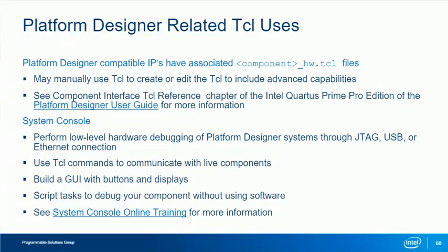With Platform Designer, there are some uses for Tcl as well. If you're not familiar with Platform Designer, that is our front-end system integration tool used to quickly build a system with custom and off-the-shelf components. Platform Designer will automatically generate the HDL for your system along with interconnect necessary to connect the components. All the Platform Designer compatible components have associated hw.tcl files that tell Platform Designer about the properties of that component.